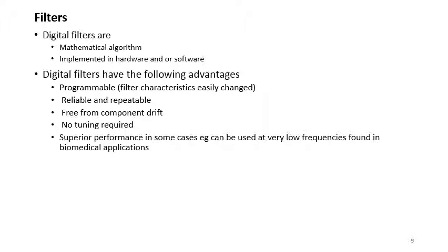That means filters are subject to ADC noise. In general, most signals of the real world are analog in nature, and to process them digitally we need to convert them from analog into digital, and after performing the operations we convert them back to analog form. So we suffer from finite word length effects due to analog to digital converter ADC noise that results from quantization.